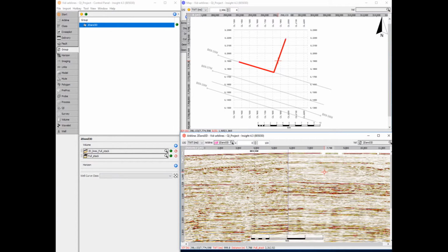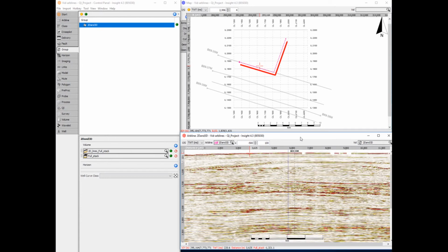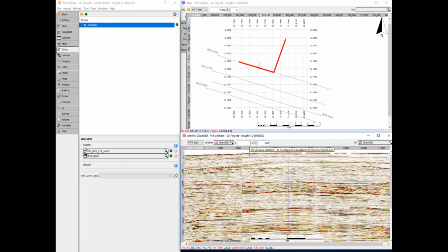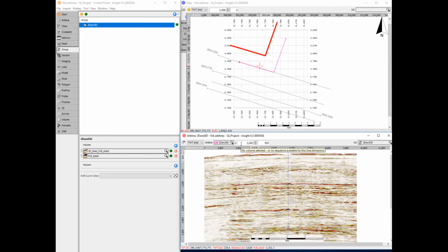Our Arbline view shows data directly along the Arbline. Sometimes it's preferable to pan through the dataset parallel to the pick line, particularly useful when fault deformation is oblique to the survey geometry. We can quickly and easily display data a set distance from the original Arbline. Let's move the Arbline plus 500 meters. Now minus 500 meters. We can set the increment to continue viewing the data at 500 meter intervals. Use the middle scroller or click and mouse drag the Arbline.